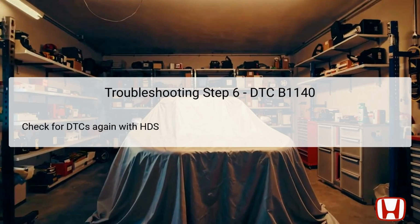In Step 6, you once again utilize the HDS to check for any stored DTCs after the power window control unit has been reset. It's essential to see if DTC B1140 is still indicated in the system. If the same code persists, it indicates that the underlying problem remains unresolved and points towards further physical inspection. Conversely, if the DTC is no longer present, it suggests that the issue may have been successfully cleared, thereby restoring functionality to the power window system.